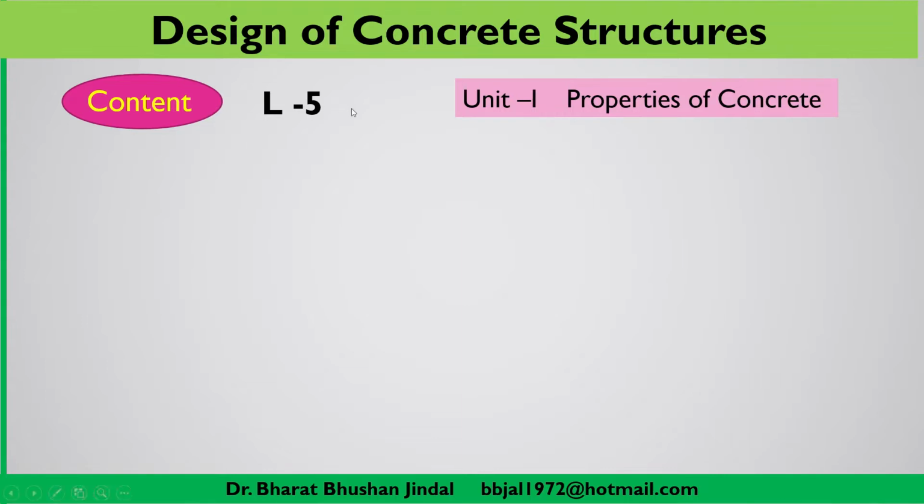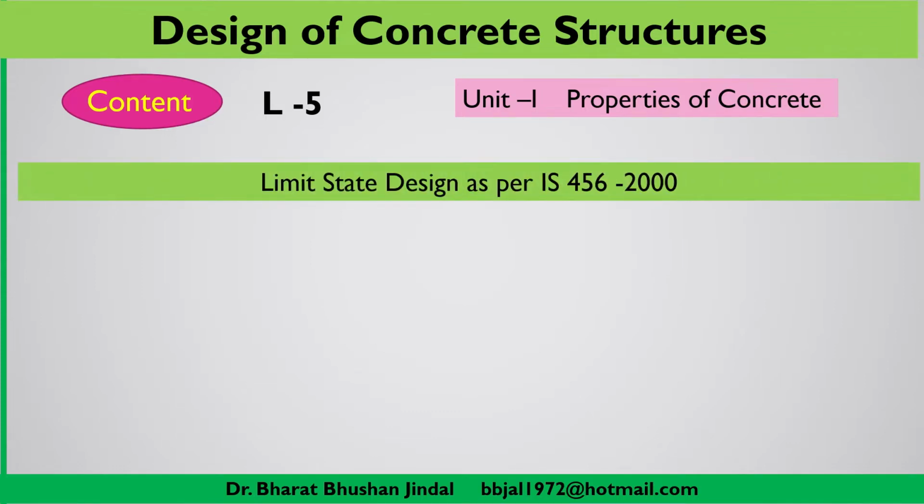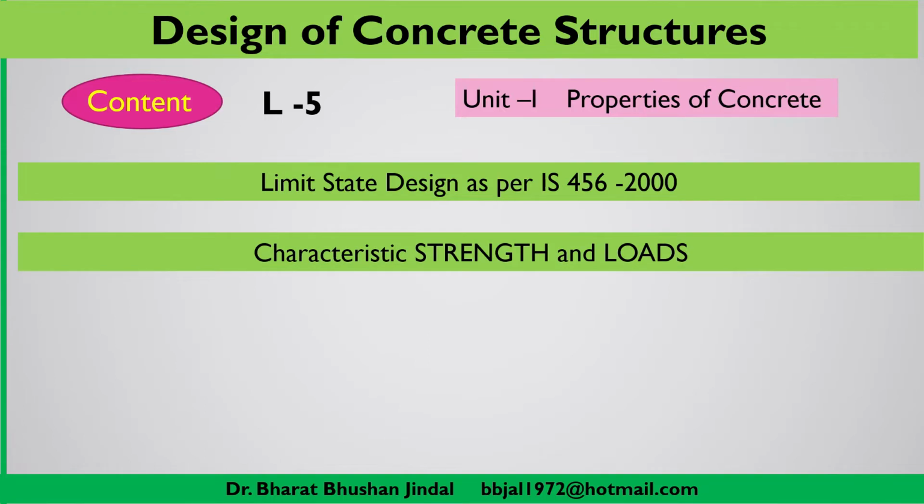So today in lecture number 5, let us discuss what we are going to discuss today. First of all, some information regarding limit state design method as per IS 456 2000. We will also discuss the characteristic strength as well as loads which any building is going to encounter.